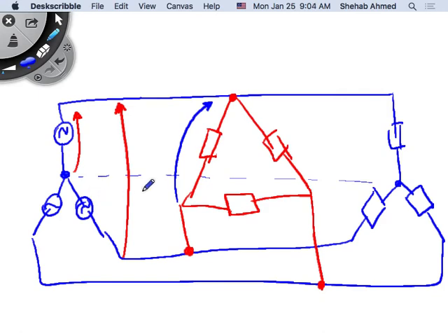So what's the solution? Yes? I was asking about the phase voltage of the delta connected load with respect to the line voltage of the source. They're the same. The phase voltage of the delta is equal to the line voltage of the source, versus the phase voltage of my star connected balanced load, which was equal to the phase voltage of my source. So it's a bit confusing now.